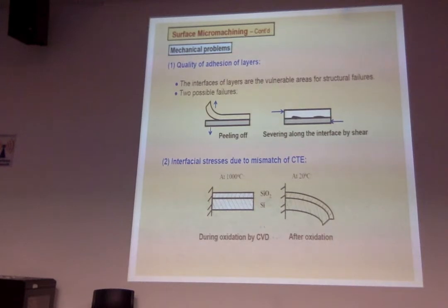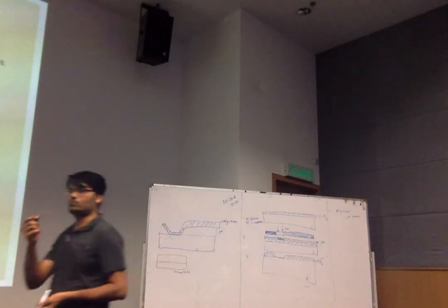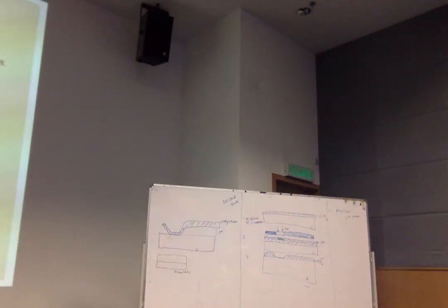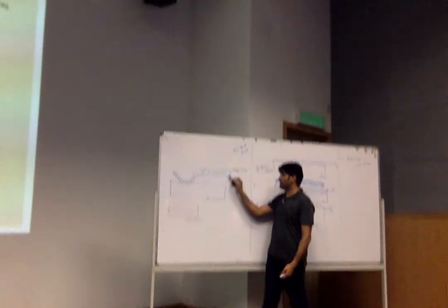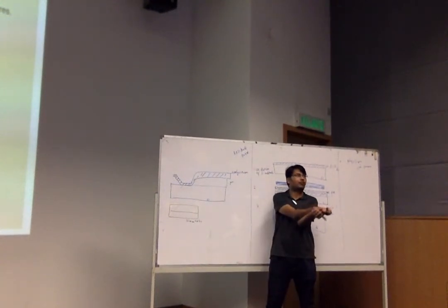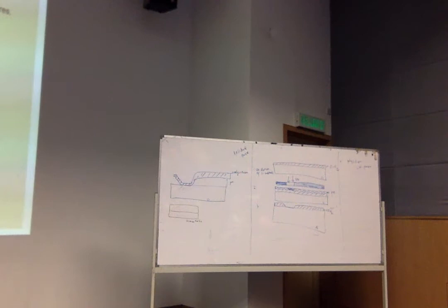The same thing happens here when we are trying to bond two things together, and if you imagine these dimensions are of a few micrometers, very small. Even a millimeter is very small. The polythene plastic bags I am talking about are millimeter-scale adhesion actually. Imagine we are talking about something in micrometers. So when you try to make three-dimensional structures that hang like this, most of the time they will just go and stick together because of van der Waals forces, and will probably end up with stiction. We call this stiction.